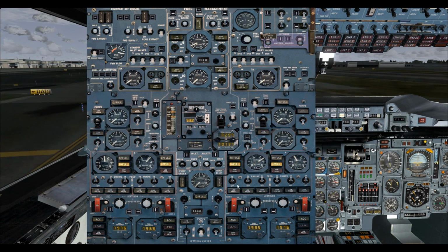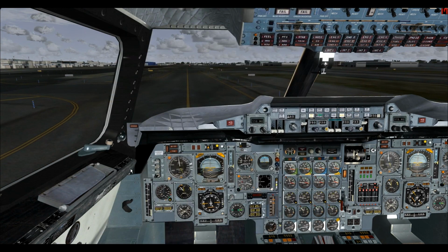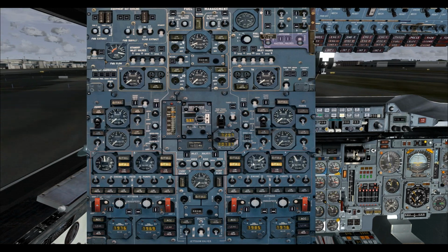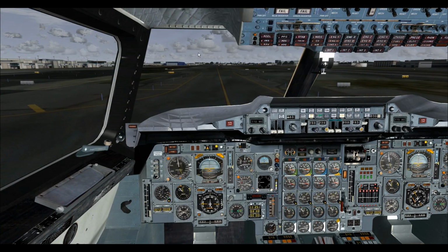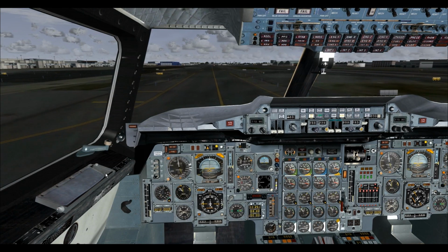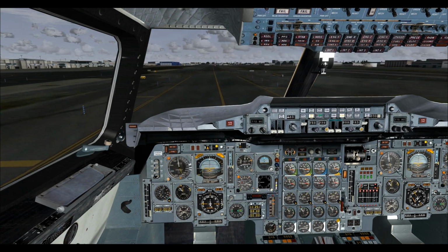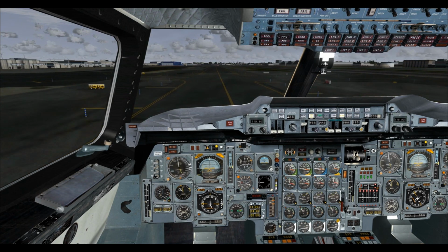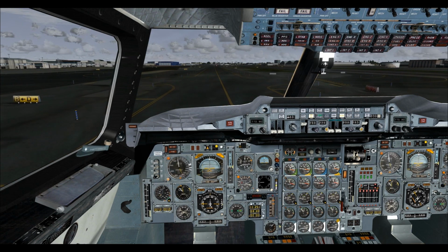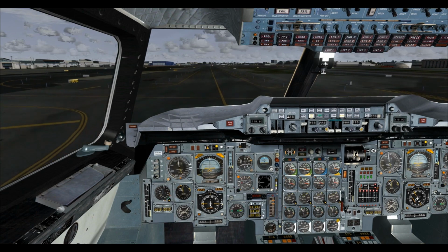And you can see now 2 and 3 are reducing in fuel, and tank 9 is moving up. So that'll continue as we finish up our taxi, making our way over to terminal 7, and I'll keep an eye on that as we taxi in, and then all we have to do is move our fuel panel to the shutdown setup, and then we're done.